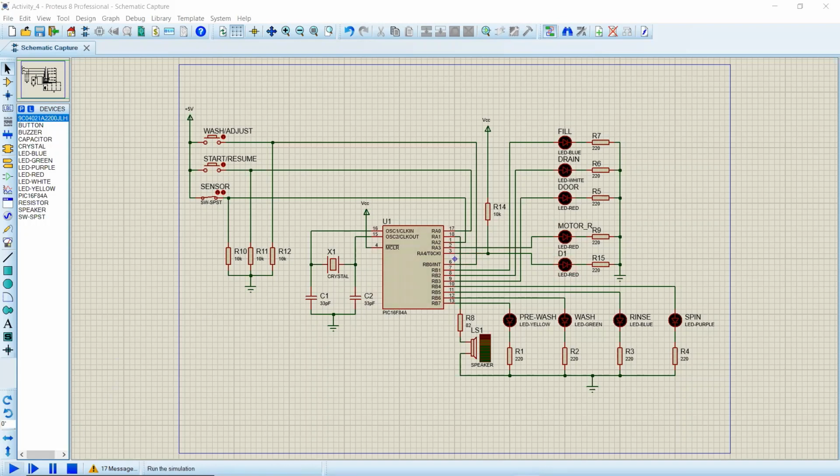Well, in Proteus, we said that we have a little detail: we have to connect a 10K resistor to VCC or 5 volts, and connect it to RA4 in order to use it as an output. In Proteus, it does not show the function of this, but in physical hardware it does. So for the purpose of this, whenever this is gray, it indicates that it's on. So first thing we have to do is check that the alarm system works.